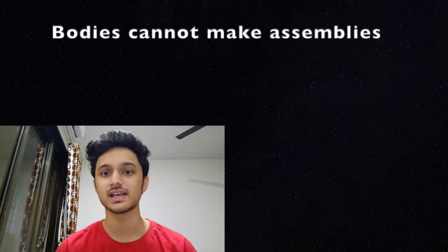So today we are going to learn components and bodies. What is the difference between components and bodies? A body is anything which is not present in the real world. For example, whatever we make in Fusion 360 at first is a body, which cannot be used to make assemblies, and on the other hand components are those which we make from bodies.